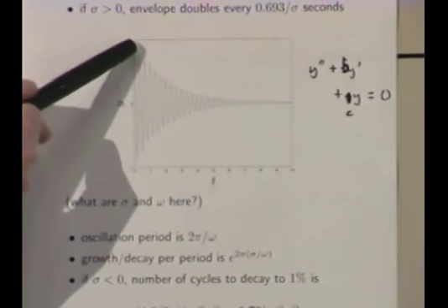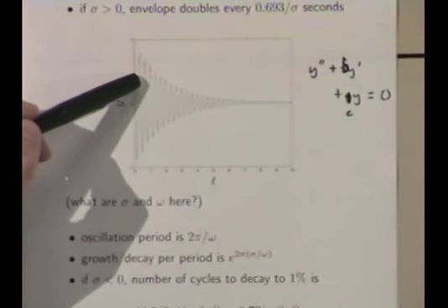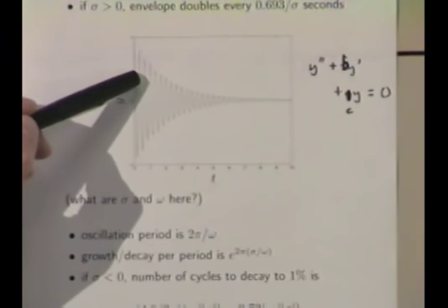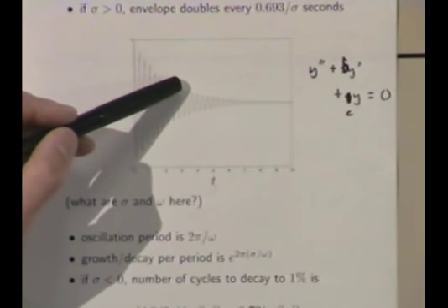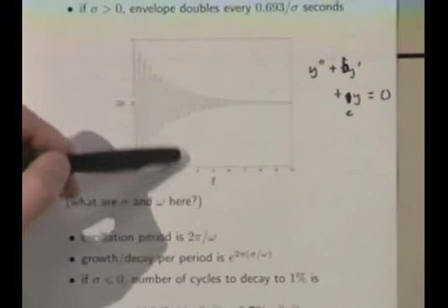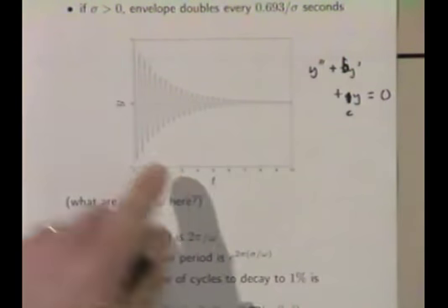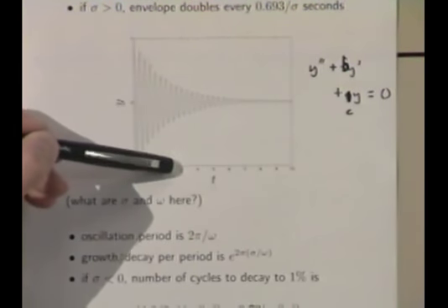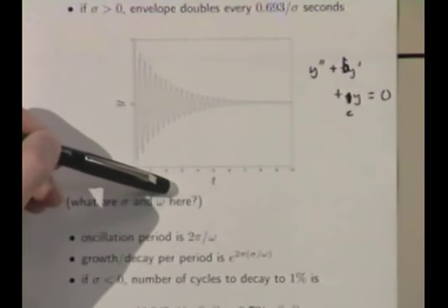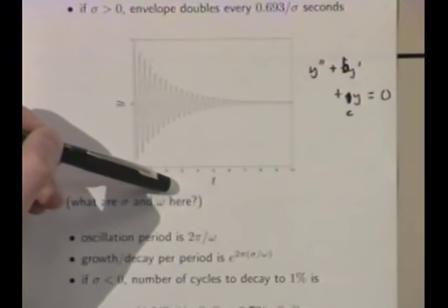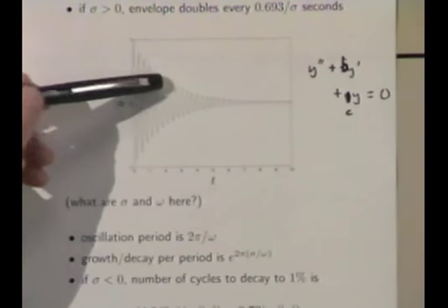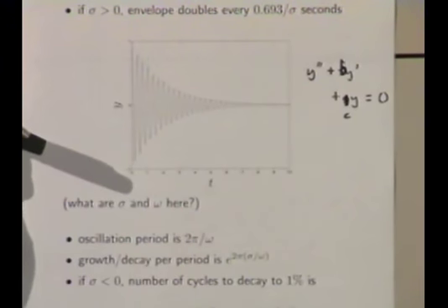In fact, to make it easy on yourself, if that's 1, you find 0.37 here, and you go across. And if doing that gives you some reasonable estimate, then you say, oh, there's the time constant. I don't know what it is. Here, let's go across there. Let's say it's 2. And so then you get sigma. Sigma is what if the time constant is 2? It's 1/2. Sigma is a frequency.